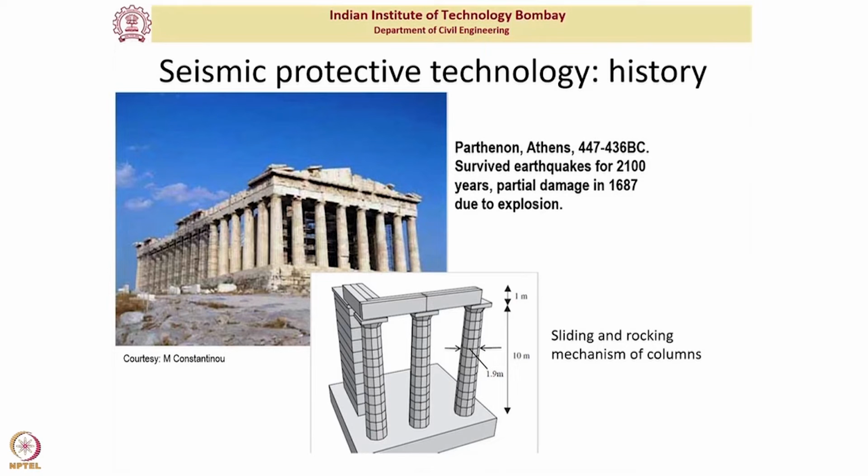Now, the design of these structures is very simple. Basically, you have modular blocks. Each of the columns, if you see, contains modular blocks which are kept over each other, and then there is a central hole through which you can have, let us say, a post-tensioning kind of mechanism, or a single rod to keep it in place.